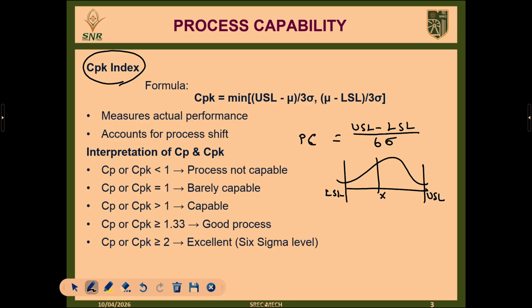While considering the process capability index, we are considering the centrality or location of the process, whether it is located centrally or is there any deviation from the central position. Suppose if the dimensions are deviated from the central position, there is a possibility for rework, there is a possibility for the rejections. So we have to avoid rework or rejections and ensure that the process is centrally located with respect to the specification, so that we can comfortably maintain our process and we can produce the quality products.